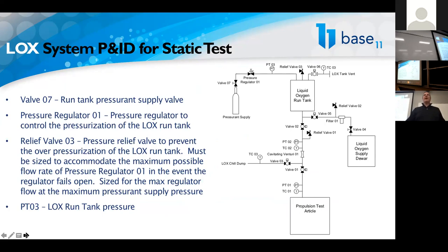Hopefully this illustrates that it's absolutely okay to say, I don't know. There are definitely issues with nitrous based on scale. Velocities and things that can work in small lines can create tremendous hazards in larger systems. A lot of that's just because nothing is actually one-dimensional, which is how we all think about flows. The larger the plumbing gets, the more opportunities there are to have a big distribution or variation in what's actually happening with the propellant.